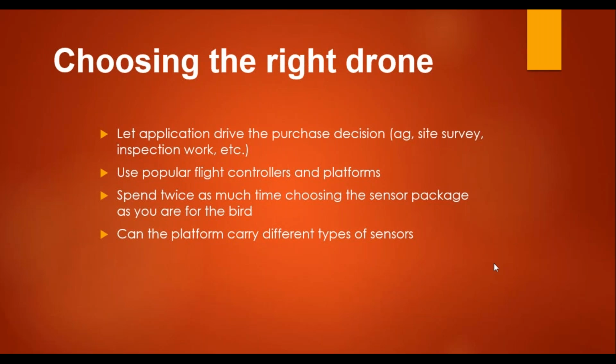And another thing is the importance of the payload itself. UAVs with greater payload are also being thought of to carry multiple sensors, and that is becoming popular. Dual imagery is being used nowadays, because thermal and RGB imaging are now commonly used simultaneously on a single platform, so that multiple, diversified data can be extracted and analysis can be done on that.